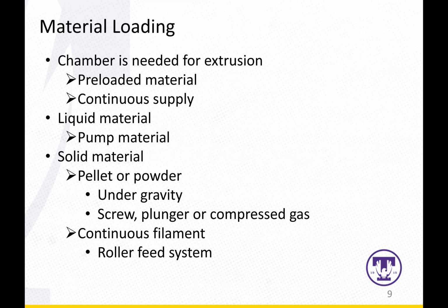And for the material loading part, basically there are two important things. The material has to be preloaded, and you have to have a continuous supply. So people are thinking about using a filament and a rolling mechanism to feed the filament to the heating unit and the nozzle, right?